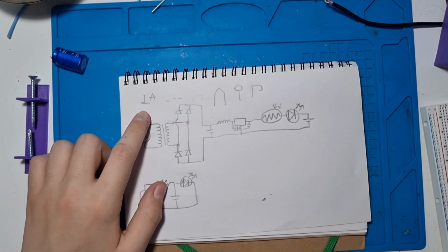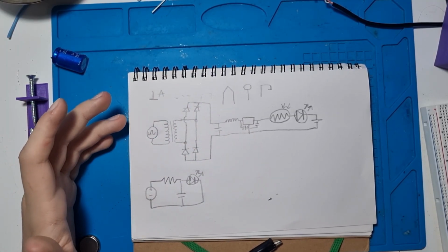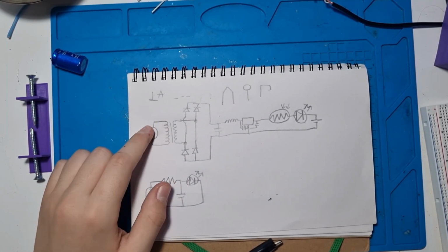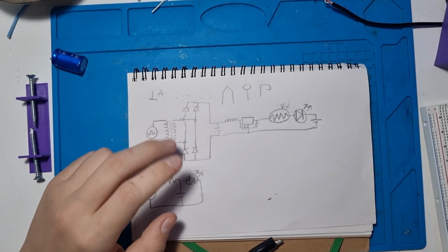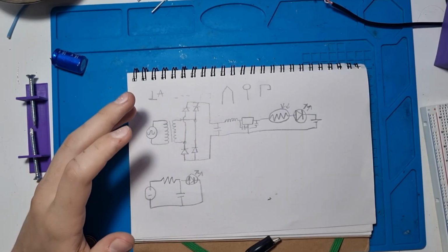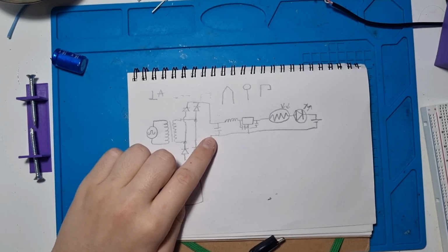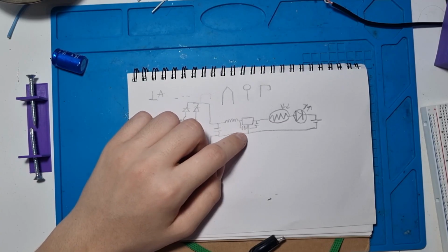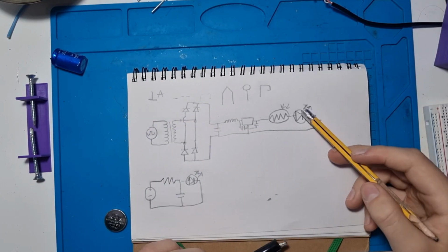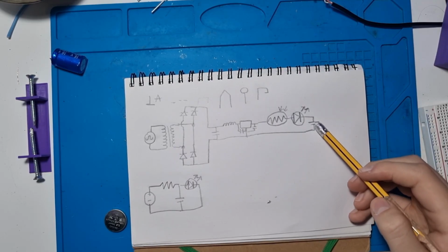We have the standard vacuum tube stuff, which is an anode, grid, and cathode, and here we have some simple circuits we could design. We have an AC source, then a transformer steps down the voltage, then diodes that allow current to flow in one direction in a circuit called a full bridge rectifier, which I have a video on, rectifies that, smooths it with the capacitor, smooths it again with the inductor, and also make sure you have real power. Then we use a voltage regulator and 2 capacitors to smooth out the output. Then we use a light variable resistor and an LED. Also right here you can charge a battery.